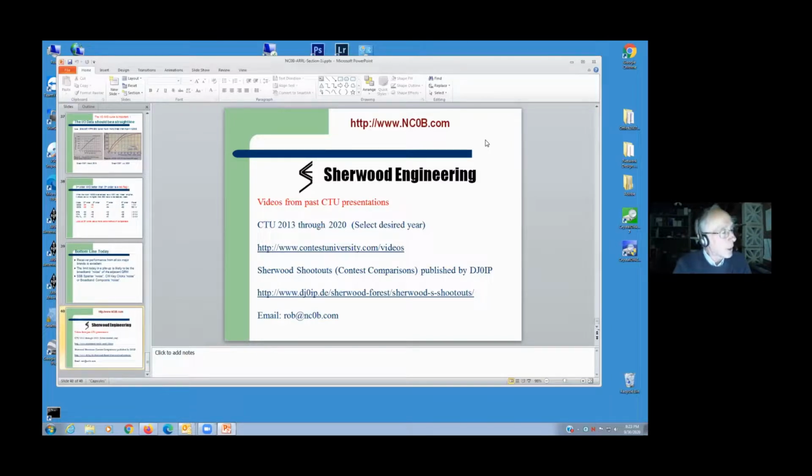I'm going to do the same thing with a couple of the ICOMs. I know I did a little bit of a test a long time ago on the Flex 6700, and every half a volt going up improved the distortion by about 1 dB. I haven't seen any yet where more voltage was worse. They've always been better. Definitely on the low side, if we're running on battery, like on field day or running portable, they really go bad when you go below 13.8. So maybe that's a case where these battery voltage increasers, even if the battery gets down to 12.5 volts, give you 13.8 out.